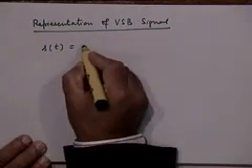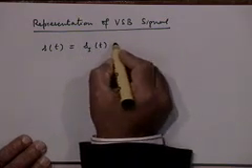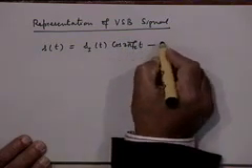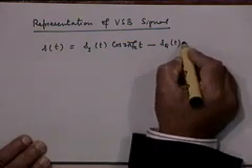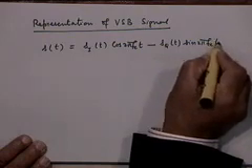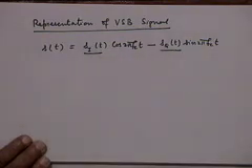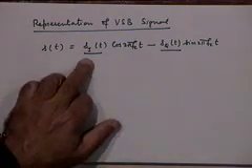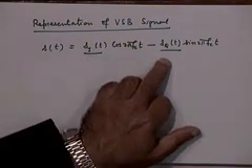So let's say it has an in phase component s_I(t) into cosine 2 pi fc t and a quadrature phase component s_Q(t) sine 2 pi fc t, right? This is an in phase component and this is a quadrature phase component which every band pass signal must have. For the DSB-SC signal, s_I(t) is m(t), right, and s_Q(t) is 0.